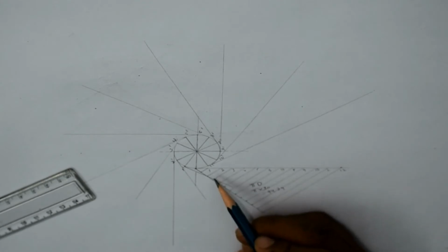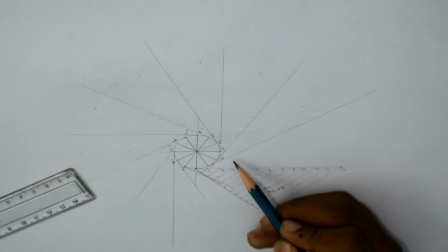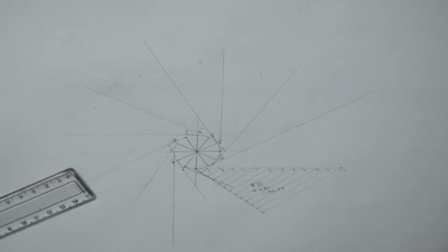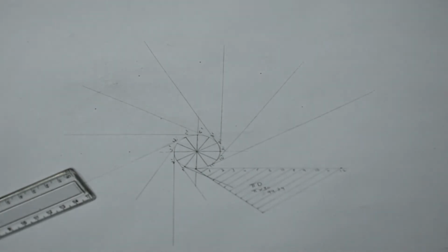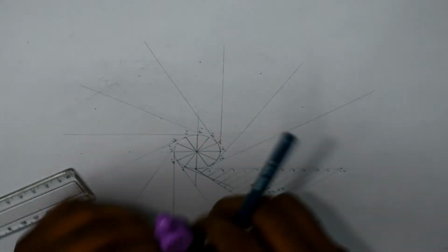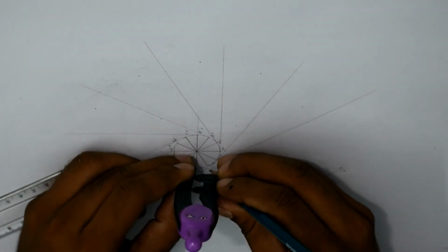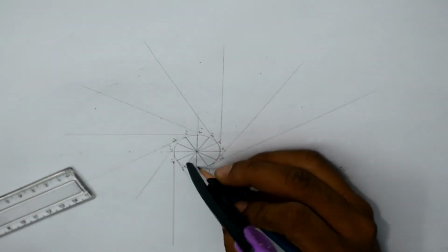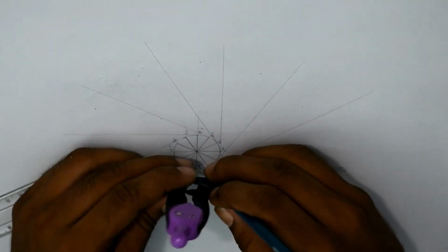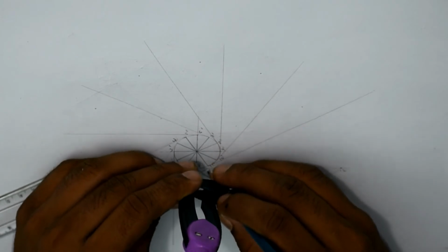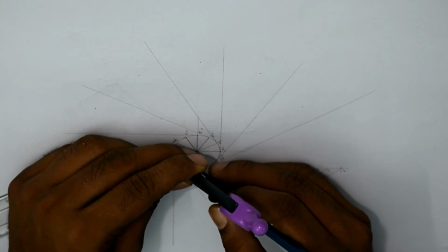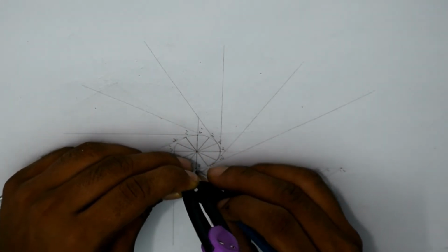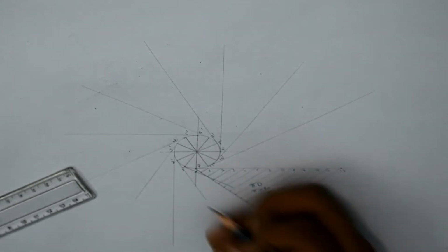See, we have taken lines from every point on the circle, and there are two tangents to this circle. This is the most important step for drawing an involute. And now what I will do is I will measure this distance from the point of the circle rolling, say point P, and I will measure this distance P to 1, and I will cut the arc from the 1 dash point on the circle. So you got this arc here.